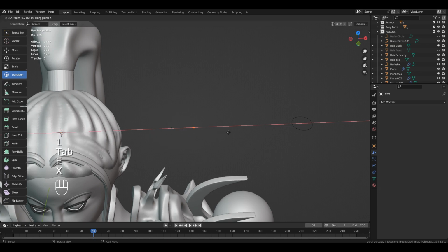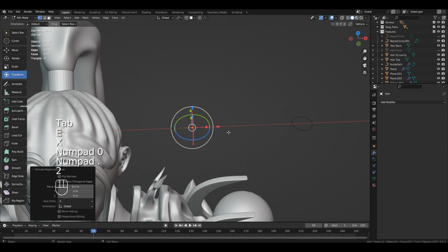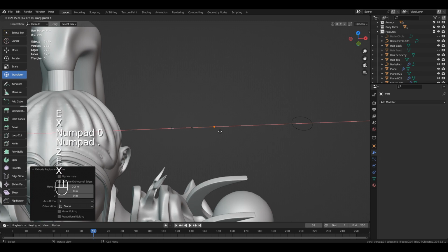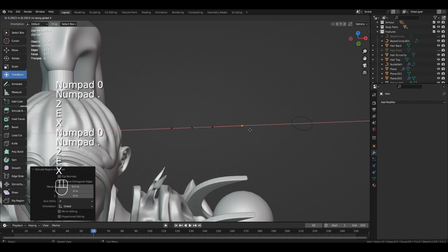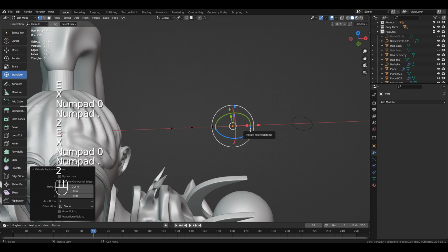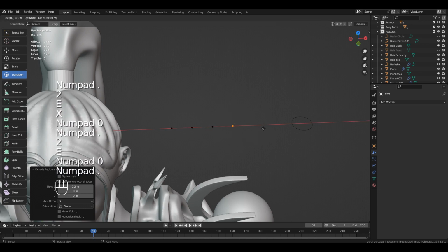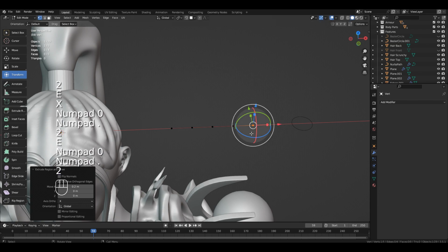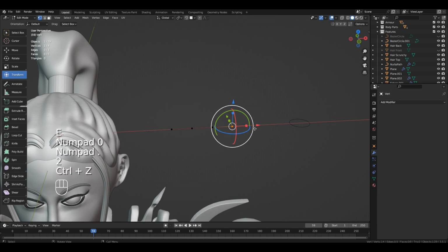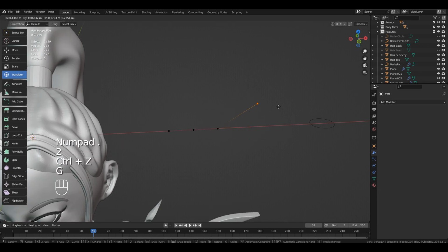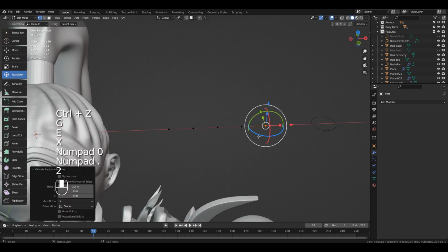We're going to do this about 4 times. You can either do this, or extrude it to 0.1 and then subdivide it a few times using the little panel in the bottom left hand corner, so you have 5 vertexes in total. This is so we can use it more accurately for the hair braid when we use arrays and modify this curve.